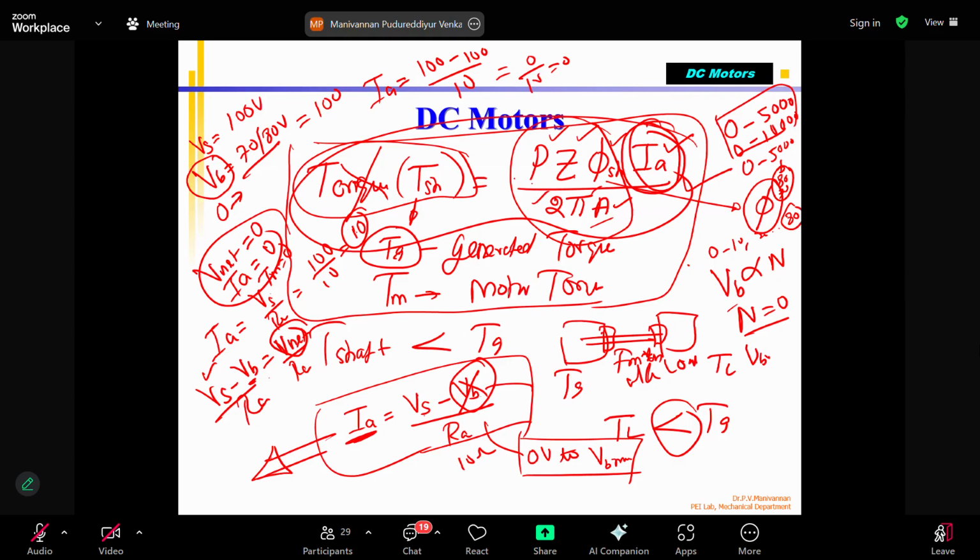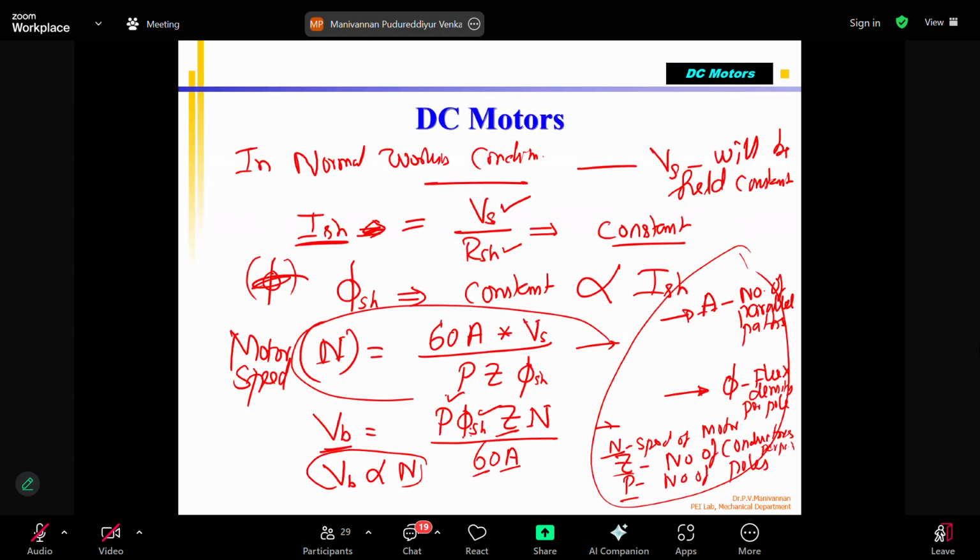And also we saw the motor speed equation. Correct? The speed equation also depends on the supply voltage. So these two things will be considered. What is the maximum supply voltage you need to apply, so that you get maximum IA at the maximum speed, so that the maximum torque is whatever torque you want. TM is that much torque. So at full speed, the net voltage is such that IA is maximum for that speed and produces maximum power and torque.